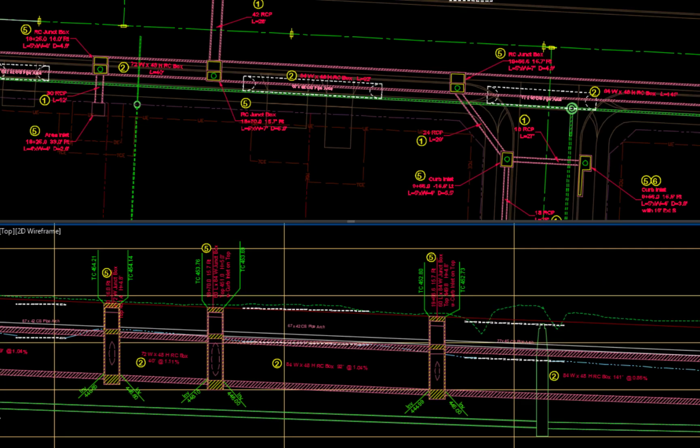The vicinity of Kincaid between 44th North and 44th South is shown in plan and profile prior to any modifications. The structures at the RC boxes along Kincaid are not actual structures per se, but are modifications to the RC box to provide openings for the installation of the curb inlets on top and the RC pipe in the sidewalls.